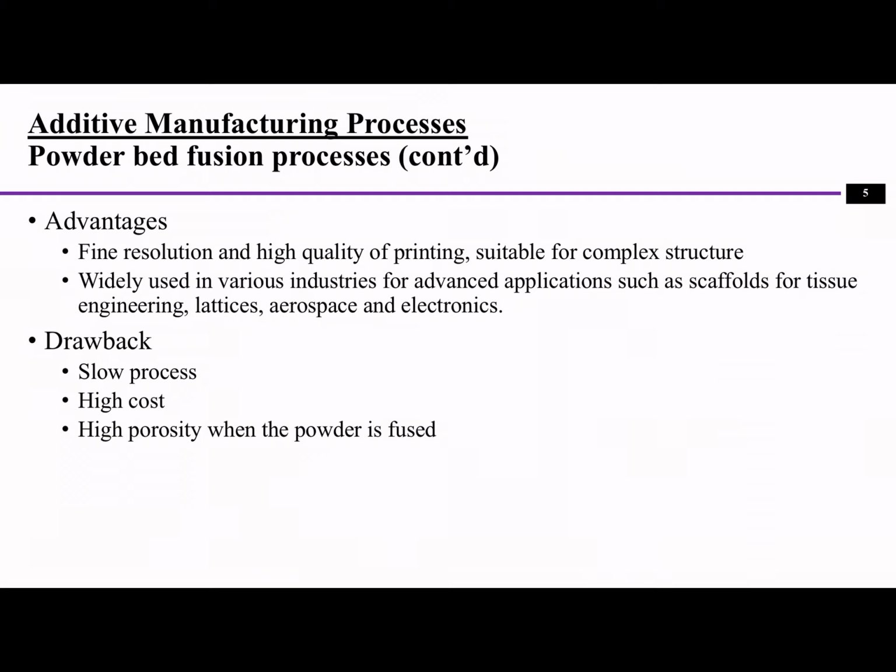Another thing is safety about these processes. Metal powders are explosive, so some of the metal powders can pose very dangerous hazards to human beings. For example, metal powder can be in the air as well. When you're handling metal powder, some of the powder will come into the air, and then when you breathe, it might affect your inhalation. So that's also something you want to take care of when you are dealing with those metal powders.